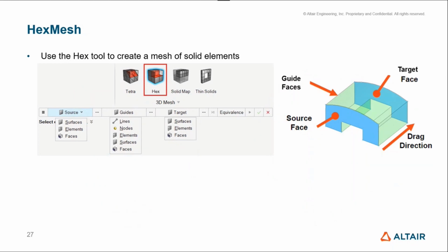And the next one is we have an all new hex mesh tool. This essentially covers our general hex mesh panel, namely the solid mesh panel, and earlier we had the line drag, elements only, linear solid. All of those cases we support now. This tool is much more enhanced in terms of selection, and we added a lot of 3D topology direct selection, which saves a lot of clicks and mouse movements. I'll show the demo for this going forward.